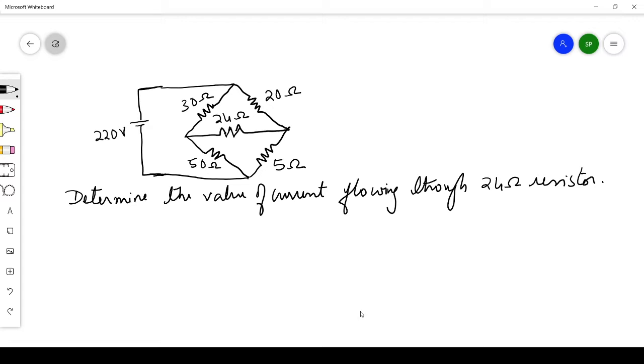Then the series resistance is the resistance of the network measured between the two terminals with load removed and constant voltage source being replaced by its internal resistance, or a short circuit if no internal resistance is given, and constant current source replaced by infinite resistance, that is, an open circuit.